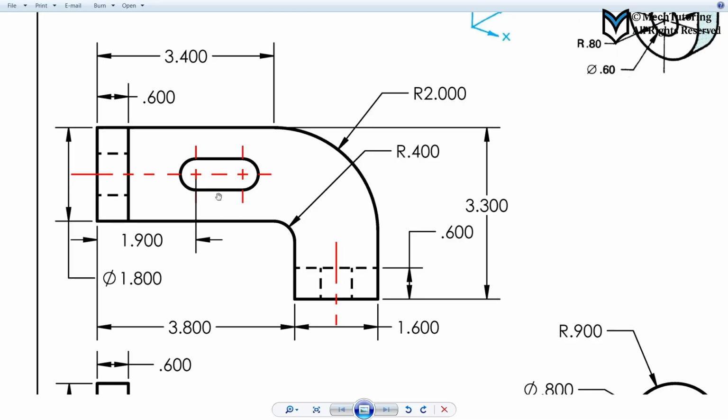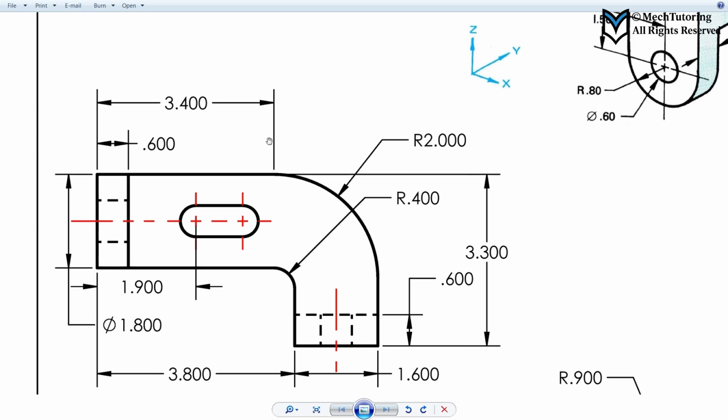You can see that there are 4 types of lines in the drawings over here, okay? There is a solid line. You're going to keep its thickness to be 0.5 millimeters, and then there is a dashed line. You're going to keep it like 0.4, 0.5. It's all good, okay? And there is a center line. You're going to keep its thickness to be 0.35 millimeters from the layers command, okay? I'm going to show you what that means, okay? And there is a dimension line. You're going to keep their thickness to be 0.15, okay?